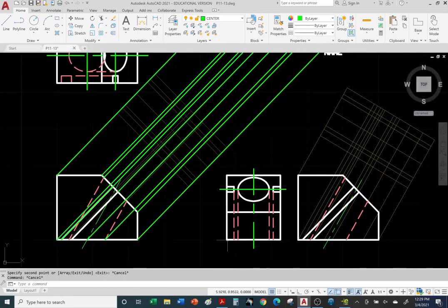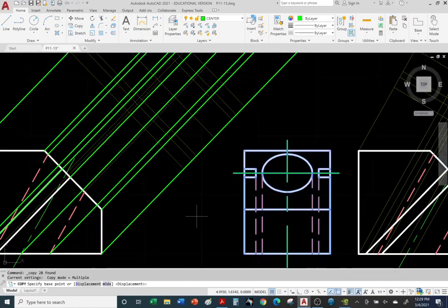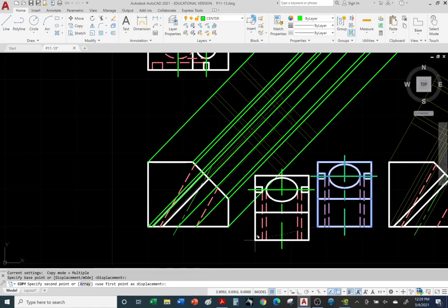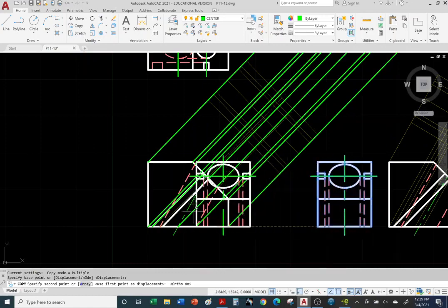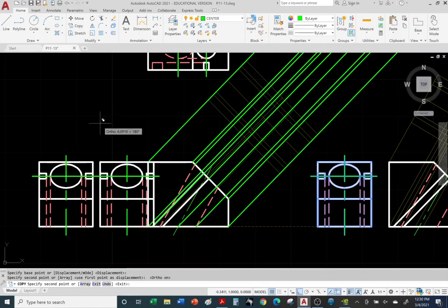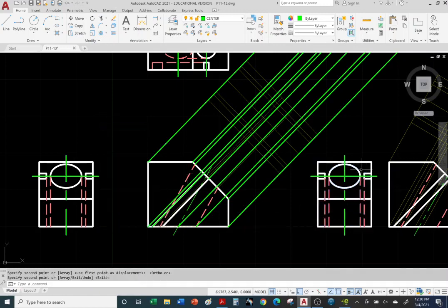And then I would take the side view. And I would first make a copy. Make a copy of the side view. I want to make a copy and keep it as a backup. Turn on ortho to keep it in line. I would keep this as a backup over here on the side. You can keep making more copies by clicking. Okay, right click enter to exit.